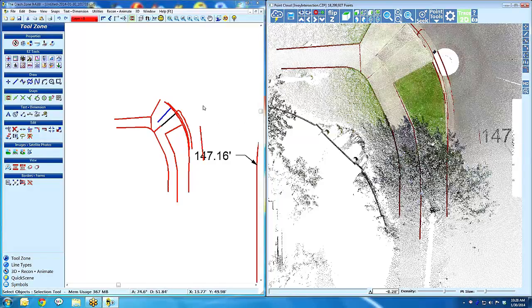That's another little trick. If you're working indoors and doing crime scene, start out by doing a top-down view and do everything in 2D, and after you've zeroed out your ground plane, that ground level adjust thing, that way you can get the outline of your room without any errant 3D glitches, and use 3D Builder in our program to give a wall height, and then you can just go back and forth. So you could switch back and forth between this mode.